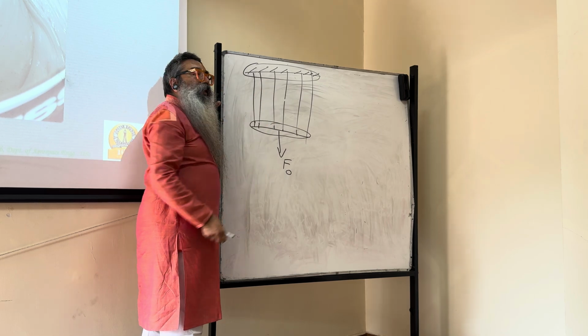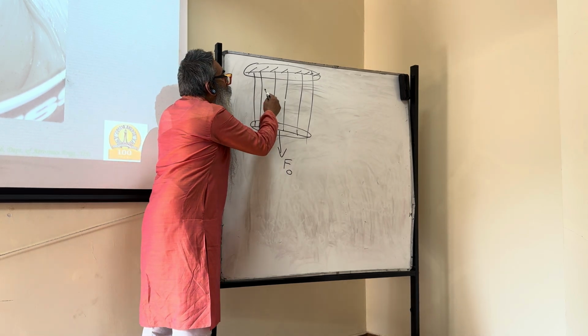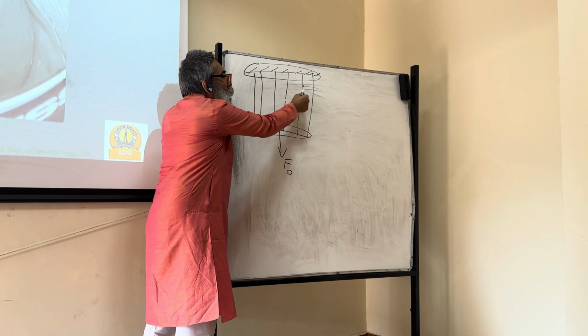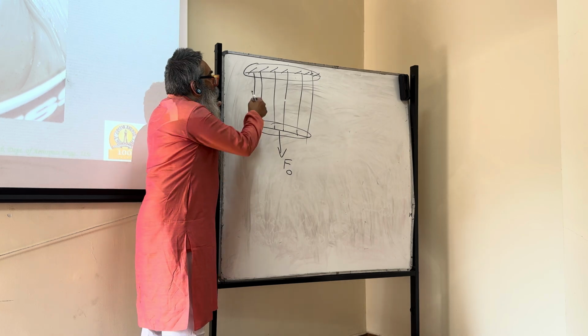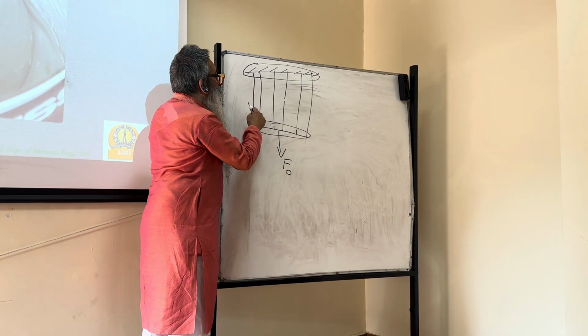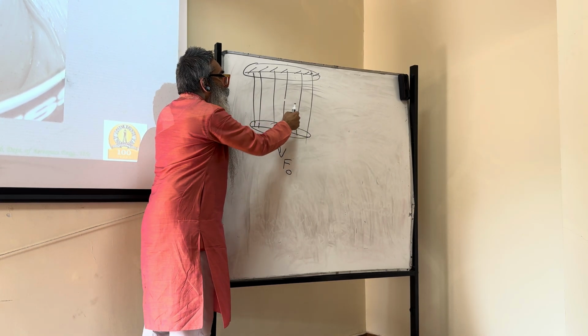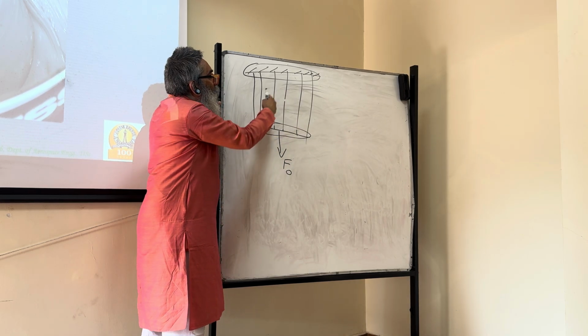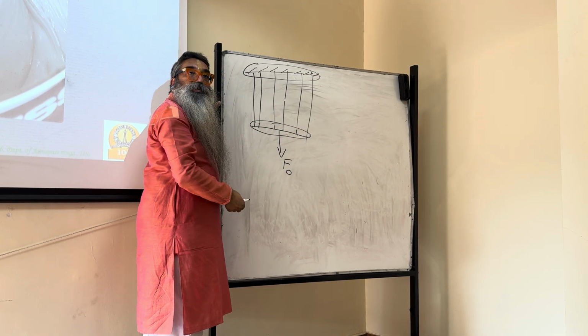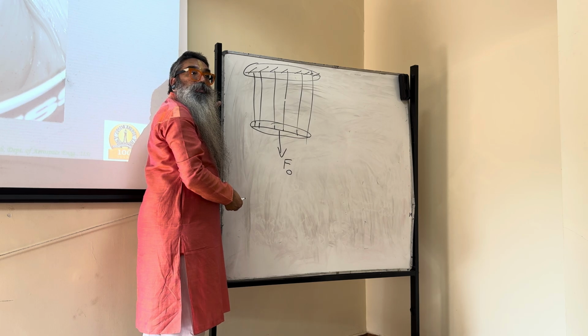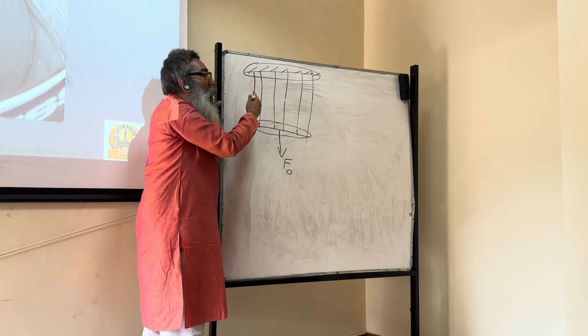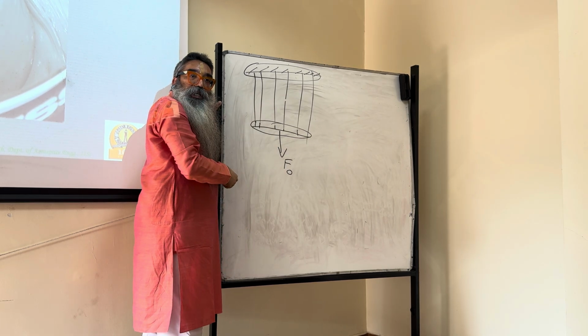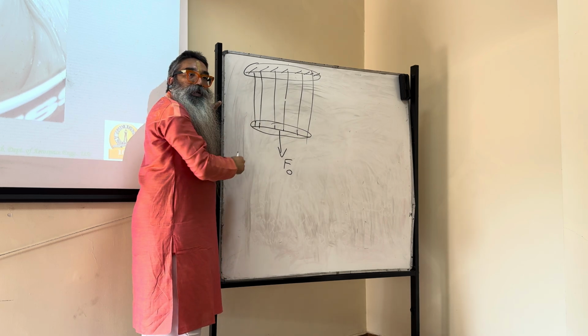So in the interiors, all of the fibers, if they have the same cross-sectional diameter, which they do, will take the same load. So if it's F0, then it will take 1, 2, 3, 4, 5, 6. F0 by 6 is the load that each one of them was taking. If there was no matrix, F0 by 5 would be beyond the failure limit of each one of those, and therefore it would have failed.